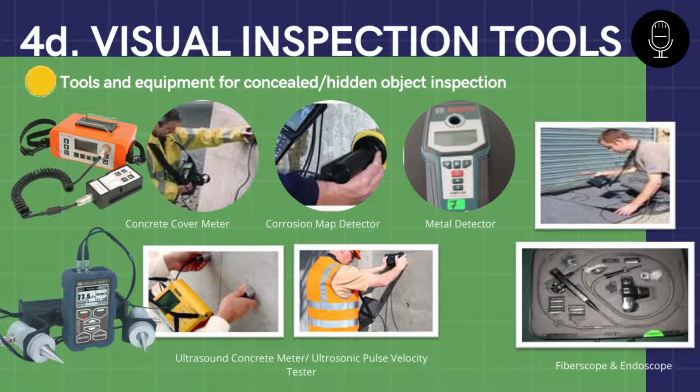Fourth, you should also know about the ultrasonic concrete meter, also known as ultrasonic pulse velocity. This tool is used in non-destructive tests to assess the homogeneity and integrity of concrete. With the ultrasonic test on concrete, three results can be assessed.